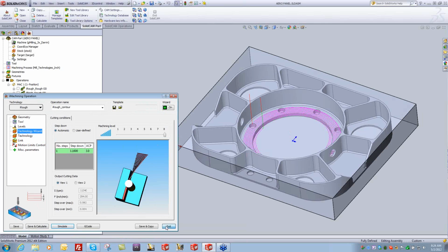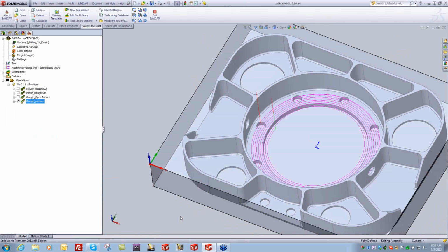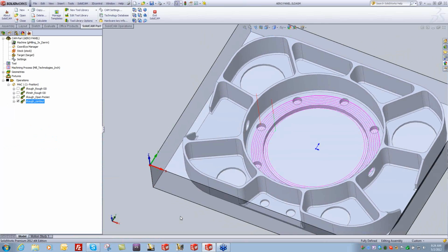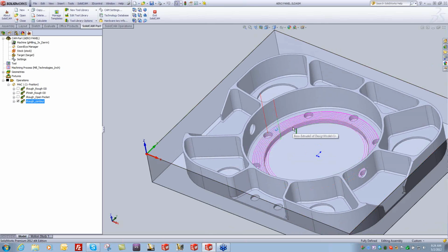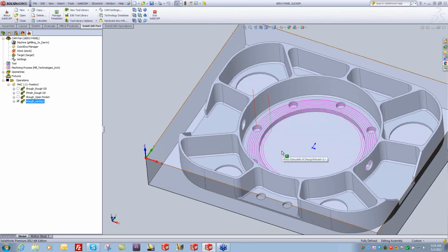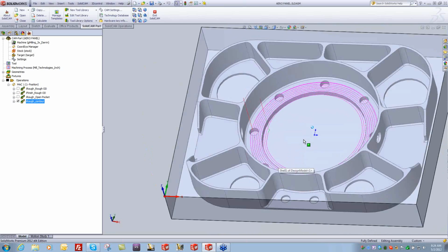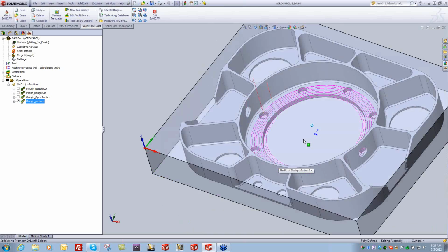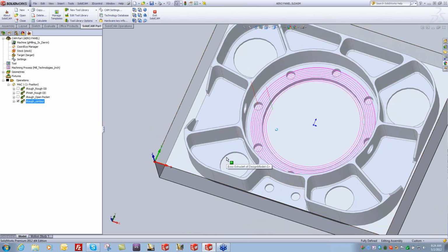All right. If you want to get into a hole and you don't want to helix down, like this one didn't helix down because we had an open edge. Let's go ahead and make any other pocket. So far, all of ours have been open edges. So we'll go ahead and create, I don't know, let's do this pocket here.